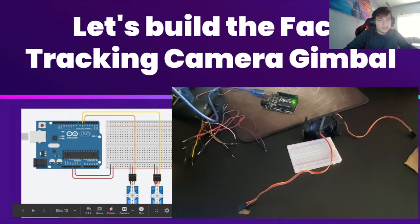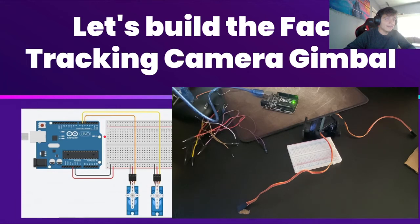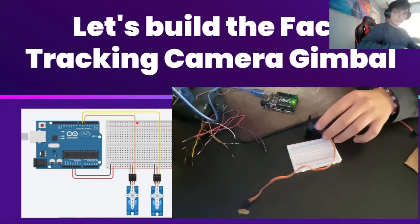And then we're going to use the PWM pins 5 and 6 that are going to be able to send the angle that we want the servo to turn to face the person or the face. Okay, so let's go ahead and do that.